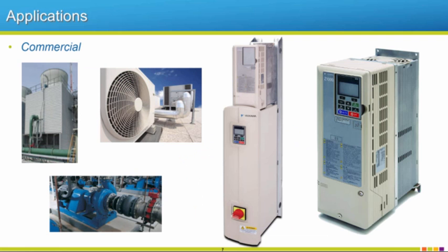So let's talk about some applications. One of the best markets for a drive from an energy standpoint would be a commercial application. The commercial market is full of these fans, pumps, and cooling towers. Even fan arrays are becoming big. And this application is a variable torque application, which will allow us to use the affinity laws, see some huge savings with the use of our VFD running at a lower speed, if possible, for our application. Most of these applications require one of our simplest control methods, so very easy to set up.